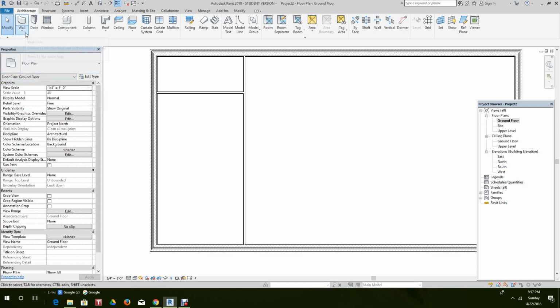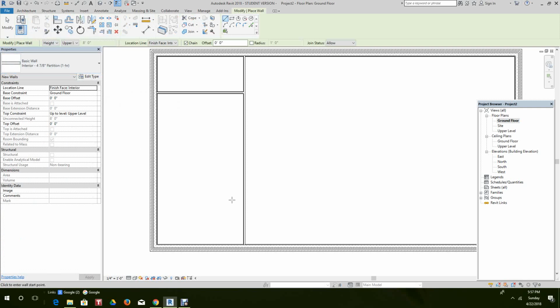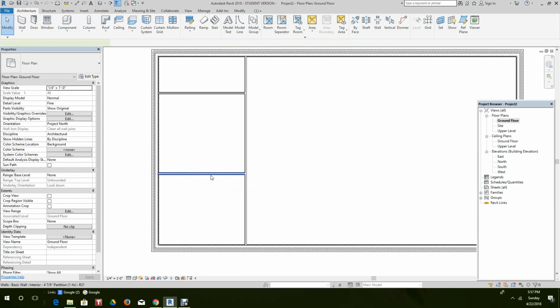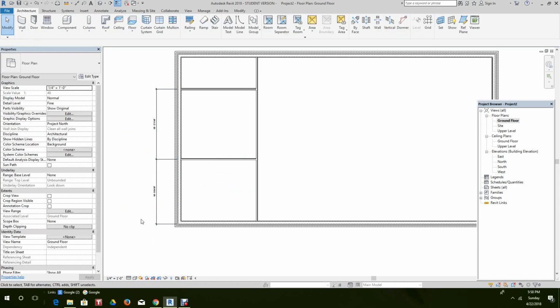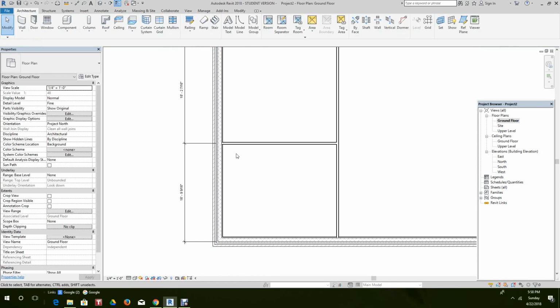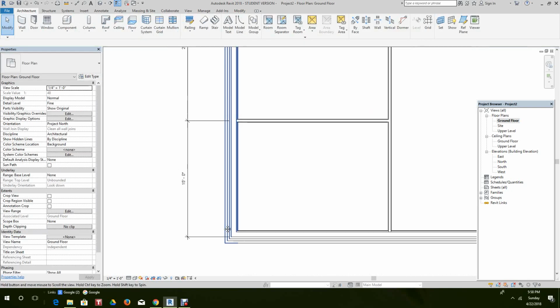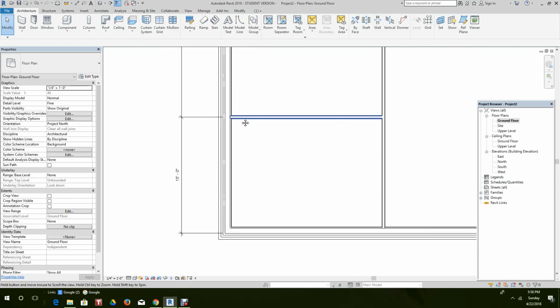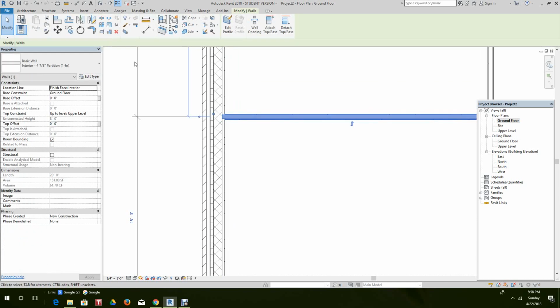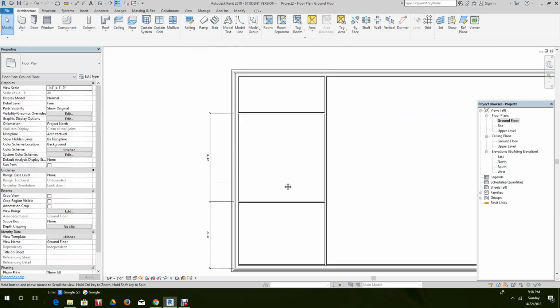Revit will remember the last wall you placed. So we've got a basic interior wall here. Okay. Now again, what you can do with these witness lines, you can also tick here, and that'll be a permanent dimension. And then if you want to round this off, let's make this 15 feet. There you have your 15-foot wall. Again, we did core faces, center faces for these walls, and the dimensions are going to align to the center. That's why they're aligned to the center.